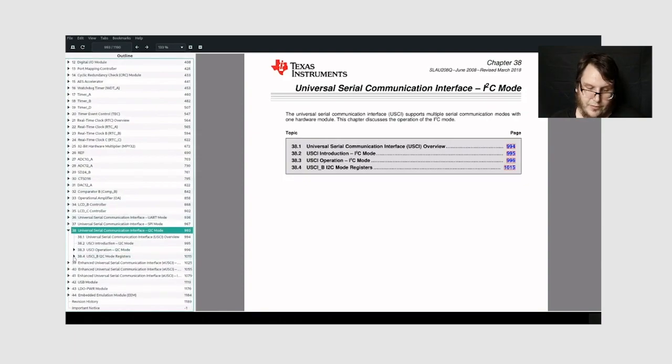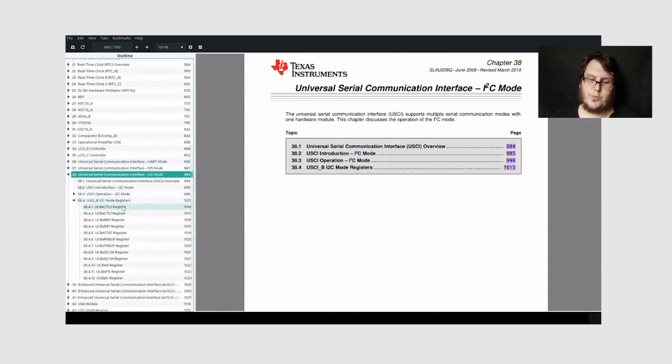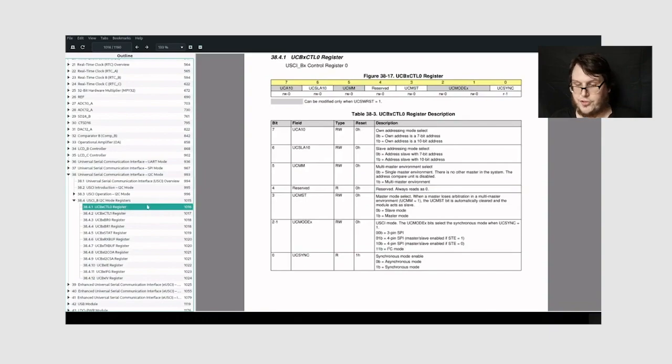And we're going to take a look specifically at the registers. I just want to show you what things you'll typically find in configuration registers. So here's control 0. Each of these is a single bit that you set in these registers, and they configure different things. If we're acting as a peripheral, do we want to use a 7-bit or a 10-bit address? If we're acting as the controller, does the peripheral have a 7-bit or a 10-bit address? Are there more than one controller on this bus?